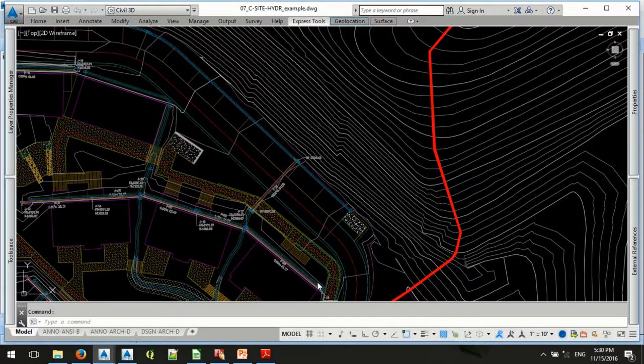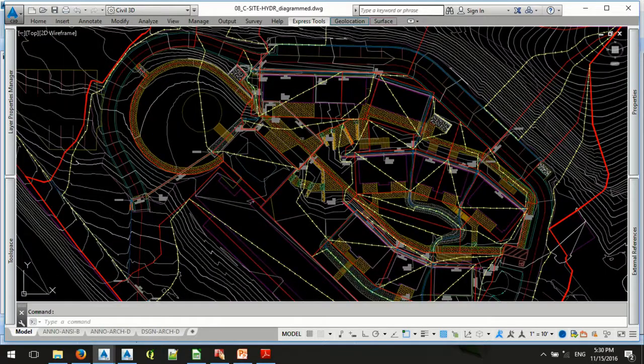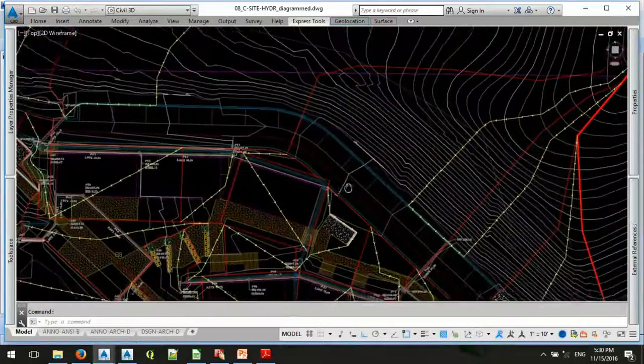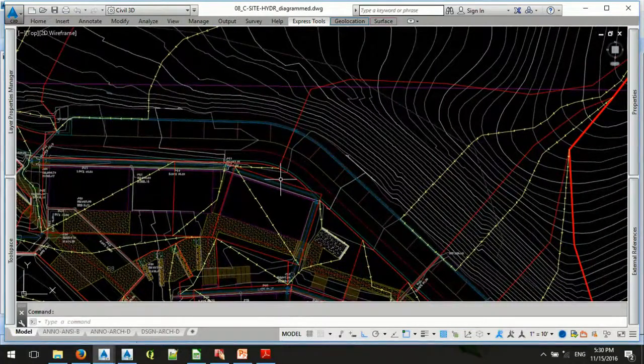And just jump forward to create this kind of a diagram, just using polyline objects. The really important thing here, because this is going to become GIS geometry, like these red outlines of the sub-basins, is that they have to be really clean. There can't be little overhangs and gaps, or it's going to fail when you try to import it. So just do your best and use the map clean function to make sure this is as clean as possible.